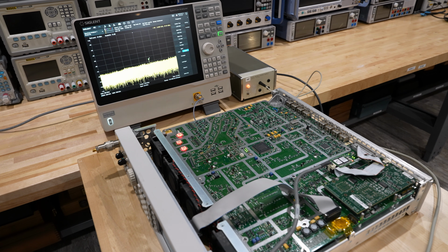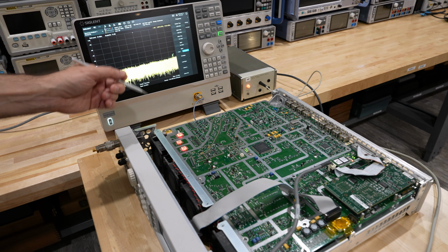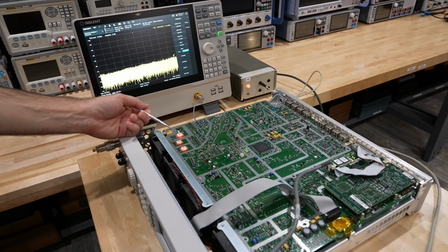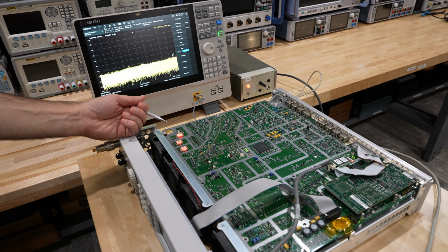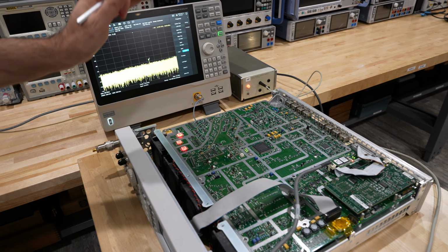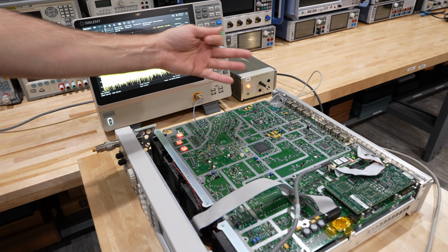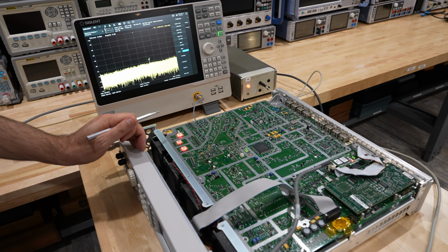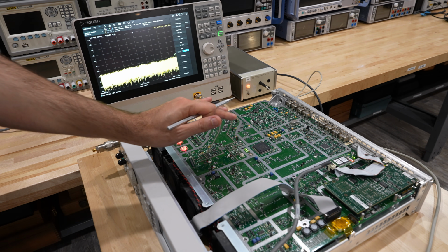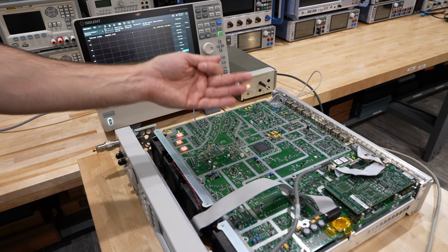And here's the first setup we're going to use to analyze and understand the circuit. So the instrument is turned on, and you can see there are actually LEDs inside of these custom Agilent packages, and they glow when you turn the unit on, which is always kind of funny to see. Right now, the instrument is set to 2.5 gigahertz. Now, most of the time, the Fractional-N loop and everything works at 2.5 gigahertz. Now, based on the block diagram, we know that that means the VCO should be running at 1.25 gigahertz.